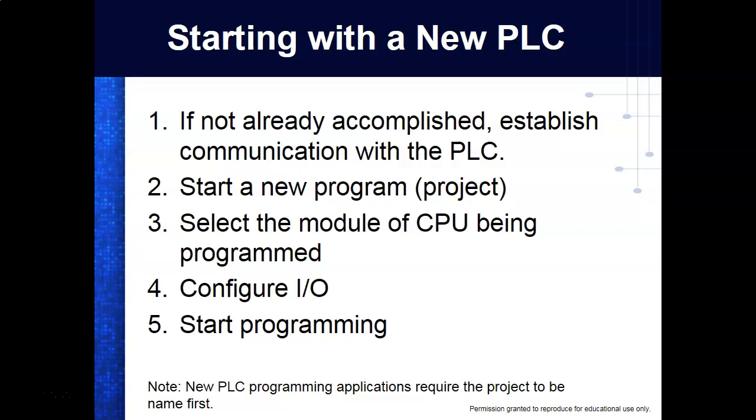And what we do, we call it offline programming. So your application's offline, and then you can come in and connect it up. So you can have all these programs stored somewhere, and you can modify the programs while your line is running, and then keep the old program and go down and download the new program when you're ready. Check it out. If everything's okay, then you're okay. Configure your I/O. We need to talk about this. We'll look at that later on, and then you start programming.